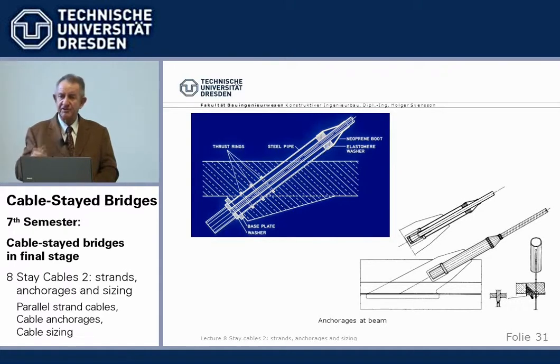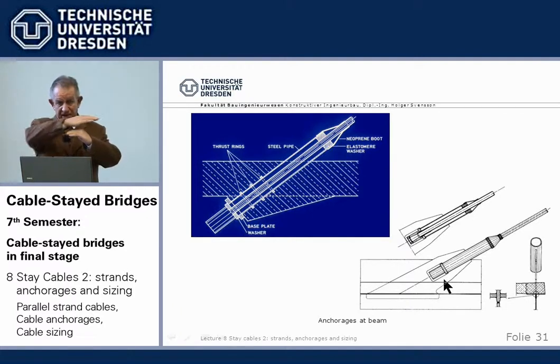This was first done for the Annacis Bridge in Canada, in British Columbia, by my friends Peter Buckland and Peter Taylor. The problem, of course, is the force transfer here. You can't weld it on top of the top flange. Then you have tension across the plate, and you get lamellar tearing, maybe through thickness. Tension is much smaller than transverse.